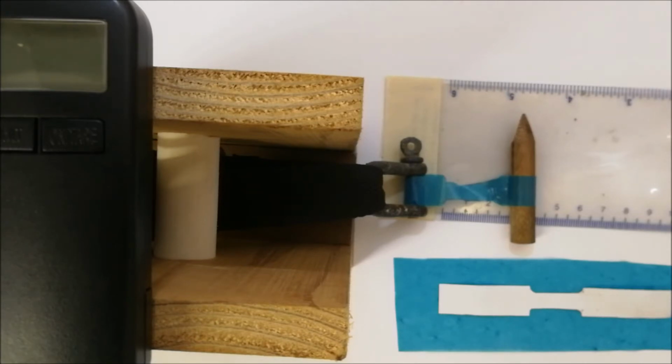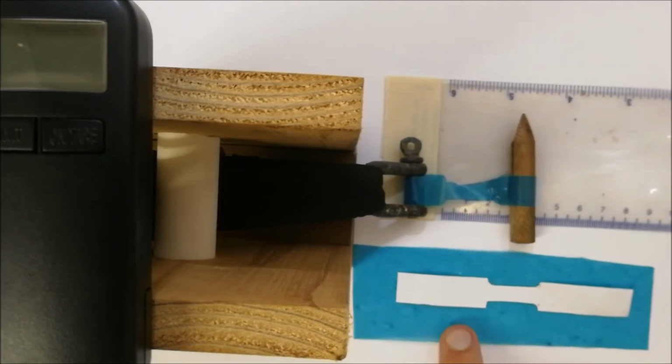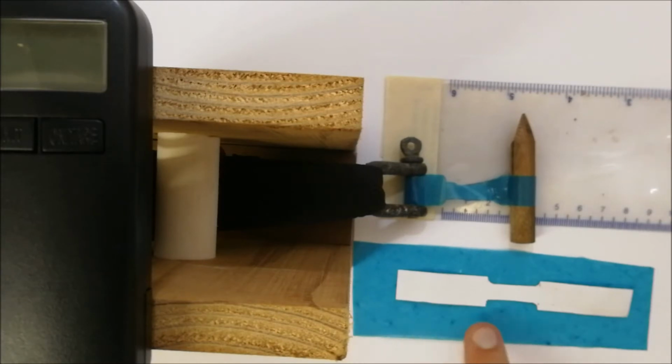Firstly, what I'm going to show you is that the samples usually used for these types of machines are in a very similar fashion, and you'll see that there's a thin necking section over here. That necking is done so that when you stretch this material away from each other, this would be the weaker spot, and it would break in this specific area.